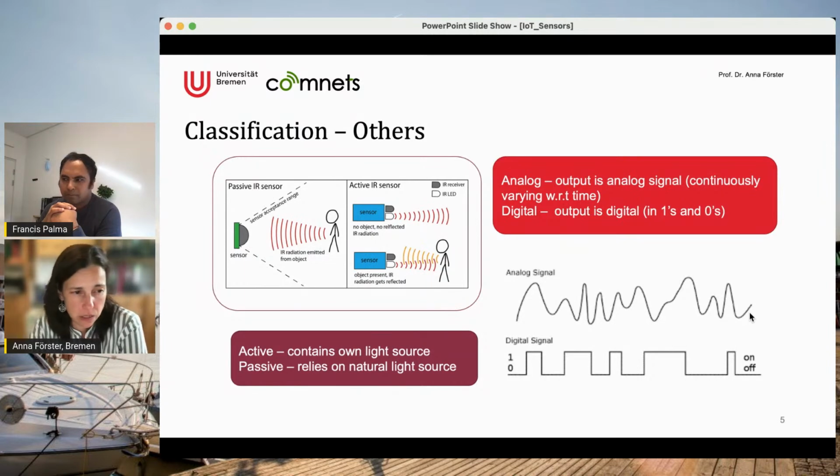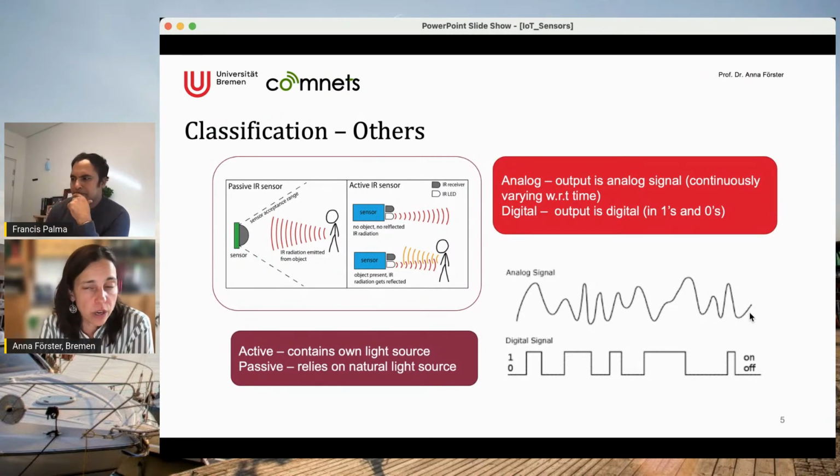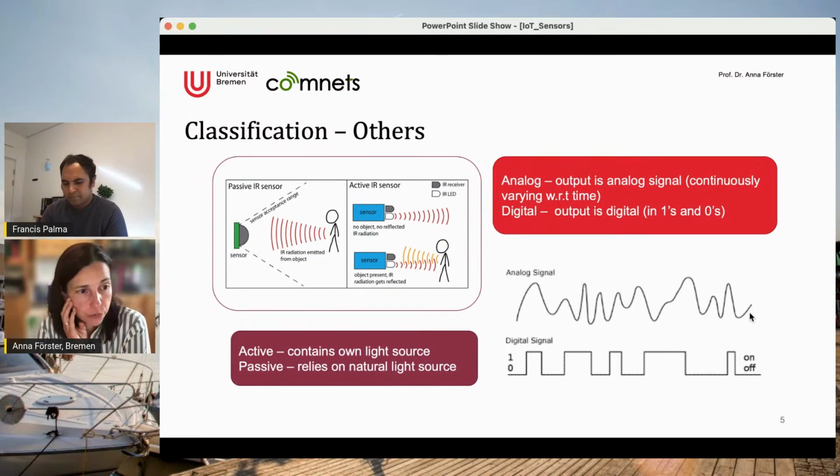And typically in many platforms, you also need to use particular pins on your hardware to connect to. It's typical that IoT platforms will have special pins which are ready to go for digital inputs, which are simpler. And you will have only a few pins which are connected to an analog digital converter, and vice versa, where you can actually use analog sensors or even actuators. So this is not straightforward, and you have to be careful where you connect it exactly.